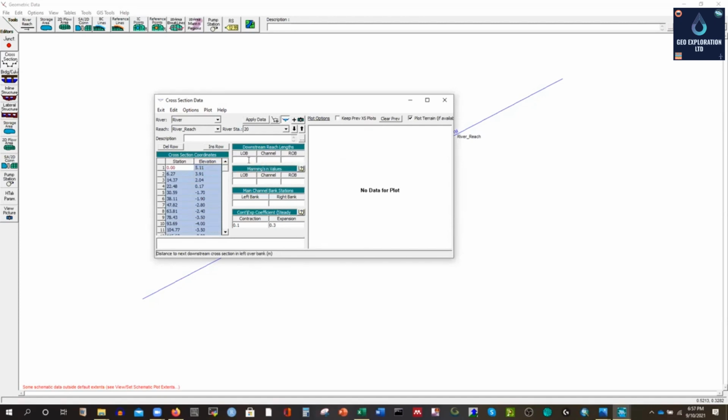So for this case, we know if it is most upstream, the next cross section is located at 500 meters. Since we are using SI units, I'm giving 500 and 500 everywhere. So what will be the Manning's coefficient? We are giving the standard value 0.023. In the channel it is different, and on the bank it is more than that. So in the channel I'm giving 0.020, and I'll use the same values for all of these sections because we are selecting a cross section that is mostly 3-4 kilometers, or more than like 10 kilometers, less than that. Okay, so that's it, we're done with this one.